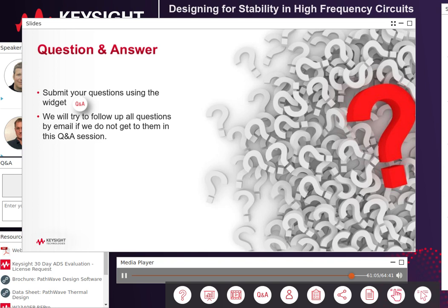So I would then need to figure out how to drive the circuit at either 3.4 gigahertz directly, or I'd have to do something like 3.4 gigahertz divided by 3 to get the fundamental somewhere around 1 gigahertz and get the harmonic to the correct frequency. So the short answer is the reason I used an AC simulation in the demo, it's just easier to get the analysis frequencies that I wanted to look at in the EM excitation.